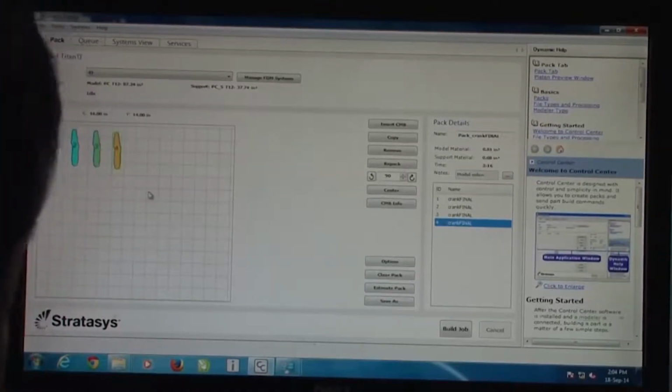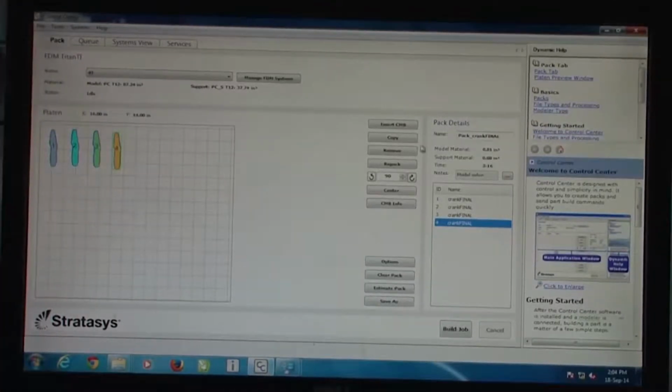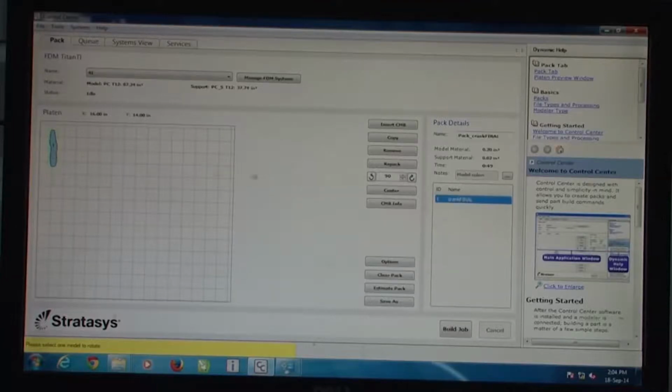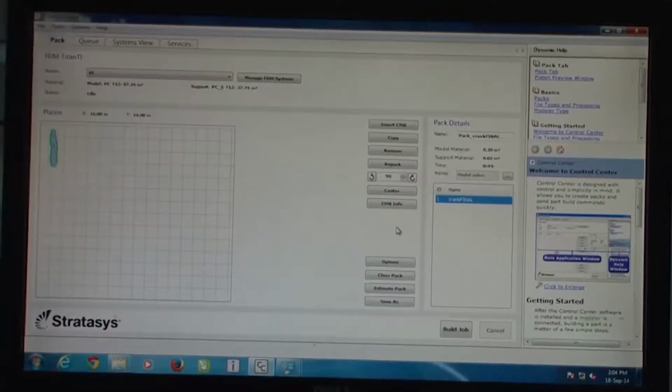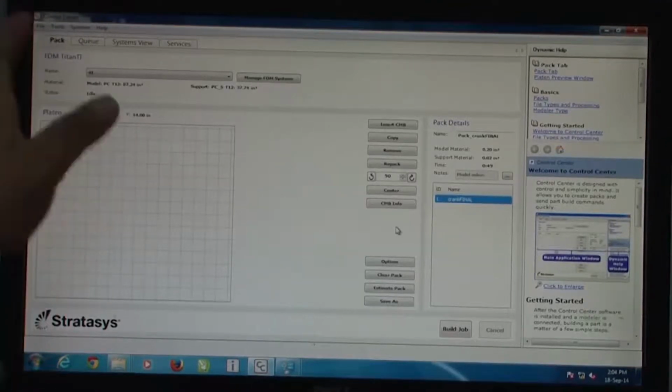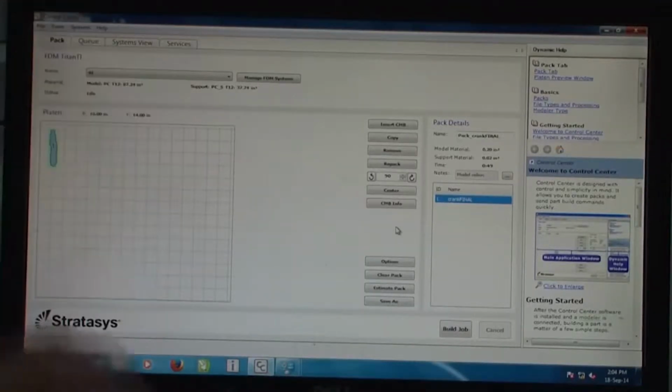So once this is done, I would just like to remove some of the things that I had made. I just want to print only one for the sake of clarity. And you can actually rotate it, invert it, you can select this particular part here, and you can rotate to any particular direction. I would just like to prefer the orthogonal direction here in the interest of the printing, so that the tool path is saved for quite some time. Every time it positions back to the XYZ is a lot of work for the tool as well.